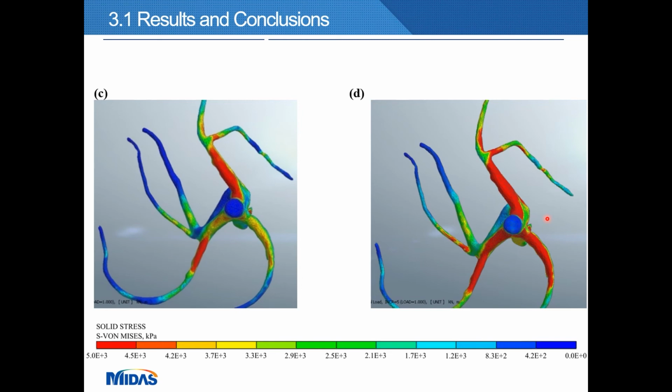So in case of extreme rainfall or an extreme storm, we will experience some failure due to an uprooting condition, and we also have breakage at the base of the tree. So it was a great conclusion of the numerical analysis. One advantage of the numerical model used in MIDAS GTS NX was that it allowed the evaluation of the mechanical resistance and bonding transfer between the soil and the rooting system.